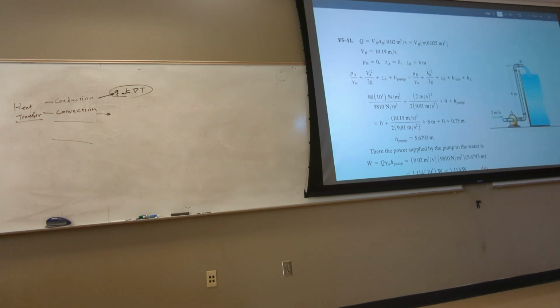pressure at B is zero. Why? Look at here. The pressure at B is zero because it's exposed to atmosphere. It's just atmospheric pressure. It's not zero, it's 100 kilopascal. But there is also another 100 kilopascal here, which they cancel out. And it's not intuitive. You see that?